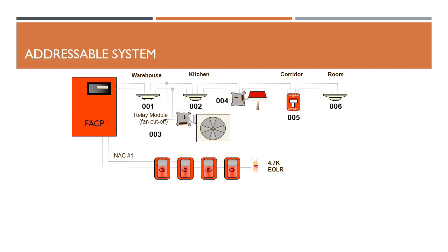Let's make a simulation of how the addressable fire alarm system behaves in the different types of events, which are alarm, trouble, and supervision. As you can observe, each of the devices in this system has an identification number or address, which is physically assigned to the device, and then the main panel by programming recognizes this address. After recognizing these devices, it is possible through the panel to assign names to each device, which facilitates its location.